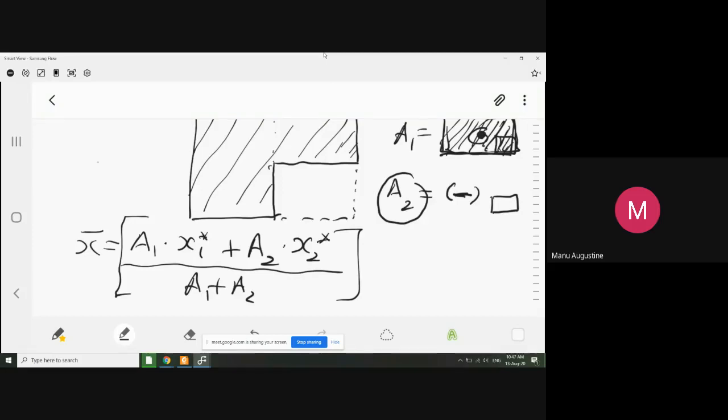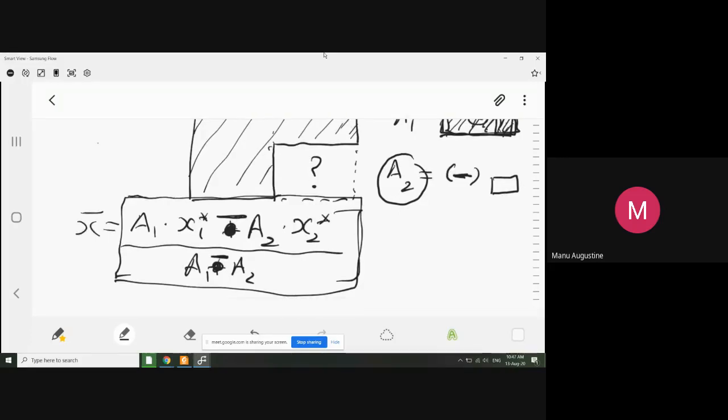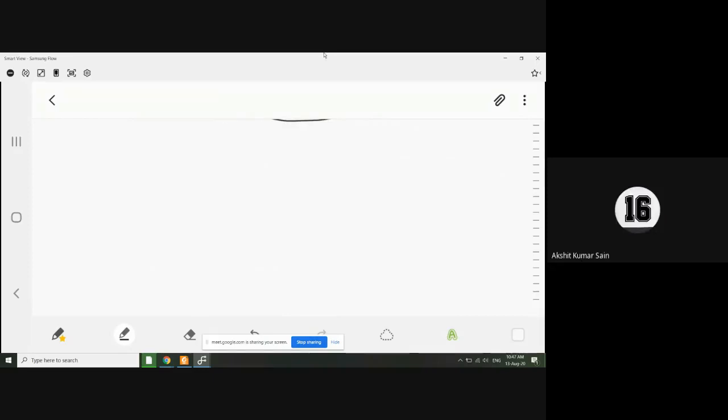Why are we putting it as negative? Because this is a missing area. So if you get a problem of missing areas, you apply the same strategy, but the only difference is A2 is put as negative. तो इस प्लस को हटा करके माइनस लिखो, इस प्लस को हटा करके माइनस लिखो, बस इतना सा चेंज है आपका. And now if we proceed to solve this,